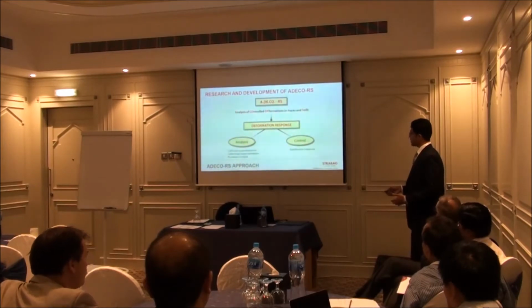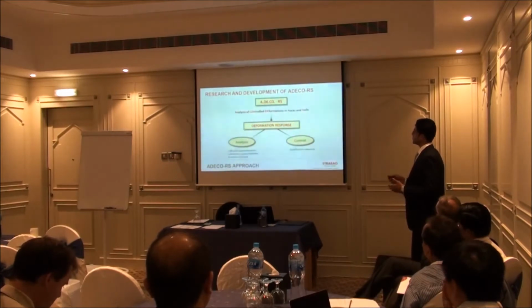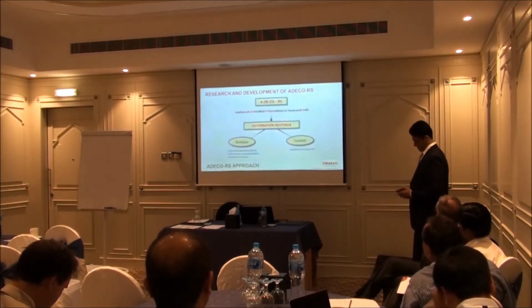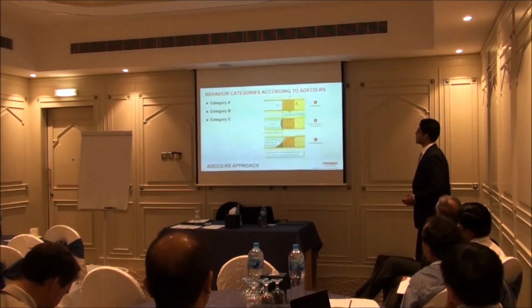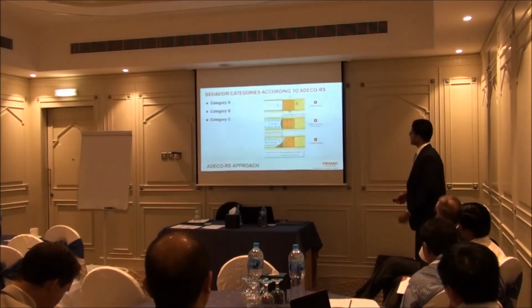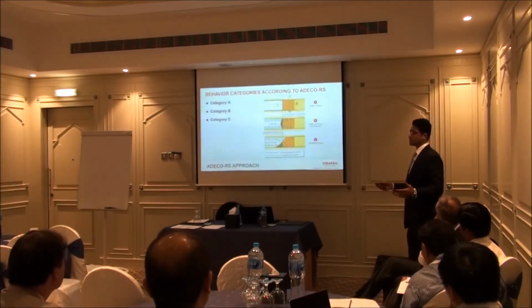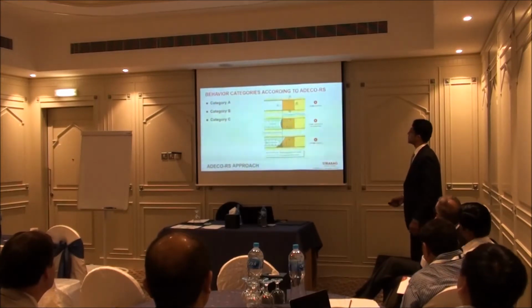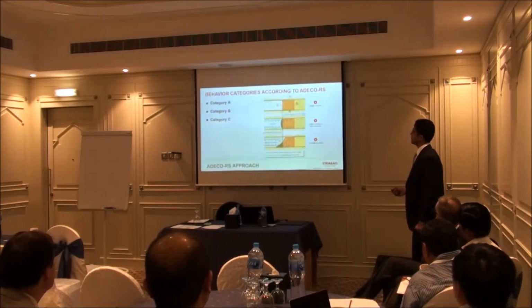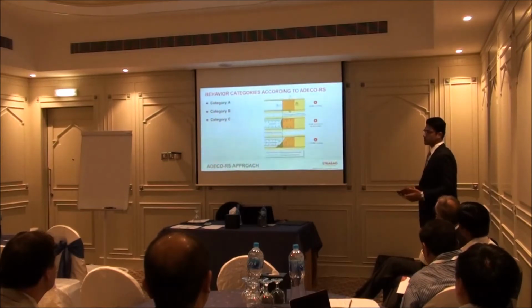So after their analysis of these deformation responses of the ground masses, they proposed control measures on how to stabilize these conditions. Based on the behavior of the rock or the ground mass, they categorized the material according to the stress-strain conditions. They categorized in three categories: first one A, B, and then C. A would be the stable condition. The B category is stable core, stable situation only short term. The C category is unstable situation.